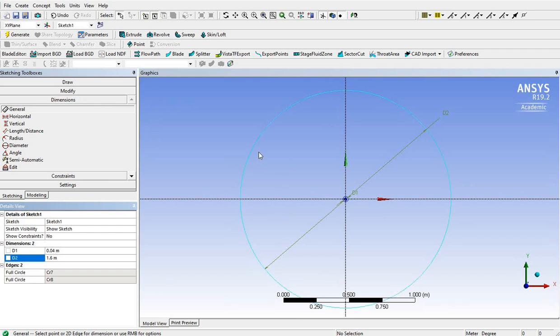And if you remember, in the first case, I told you guys to make a comparison with different meshes. So that is one way of validation. And if you are doing an external flow, another thing you need to compare is the domain sizes, because we are guessing this external domain, this 1.6 meter external domain, is good enough, but we can't be sure. So what we can do is take a look at the velocity contour plot and pressure contour plot and make a guess if something is hitting back.